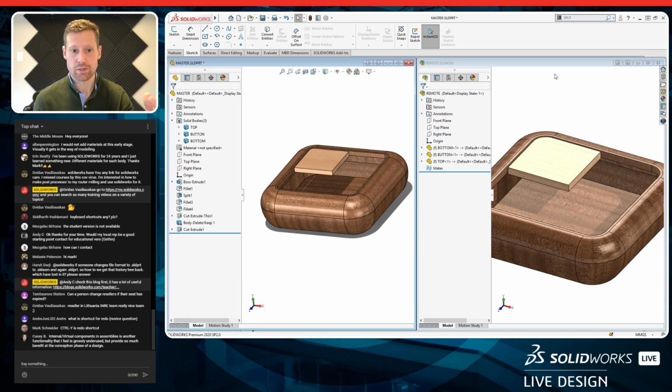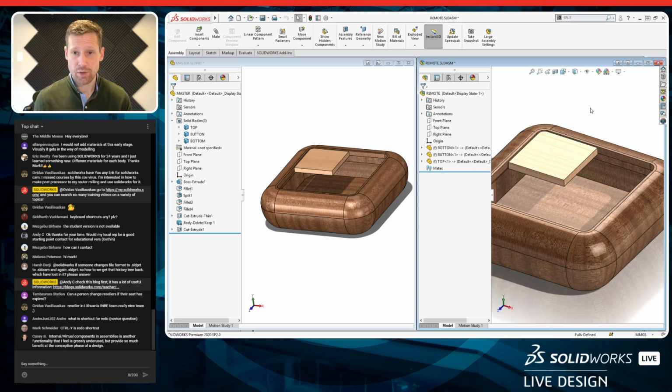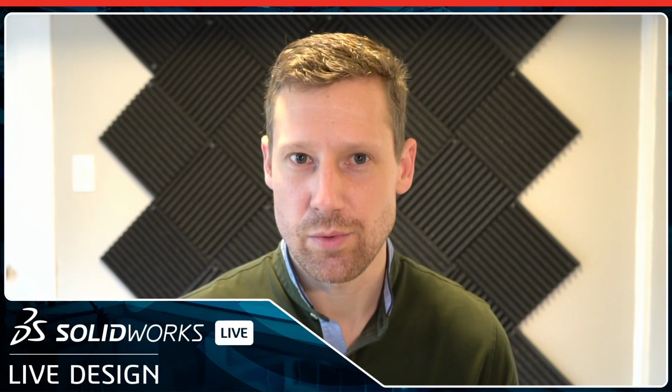Now again, what we're going to see is once I open up remote, it's going to propagate all those changes through the parts and go to remote. There we go. So that's pretty amazing. We were able to build intelligence into this master model so that any kind of changes that we make propagate to those parts and eventually into that assembly. Okay, so we went through 3 different methods of master modeling techniques plus an extra one, and I was talking about it initially, what is the secret to the best designs, but I haven't shown you that yet.